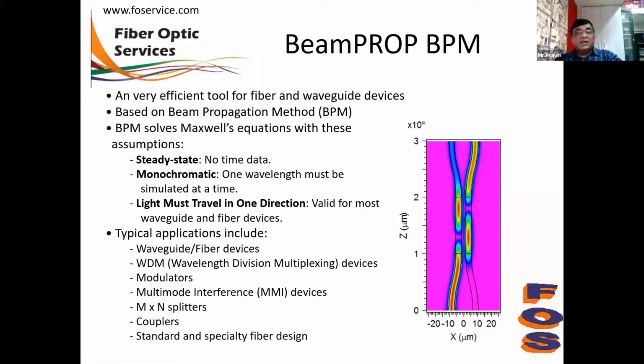In BeamPROP, only one wavelength travels at a time, and light must travel in one direction. So this is the BPM based technique, and it is suitable for waveguides, WDM multiplexing devices, modulators, multi-mode interface devices, splitters, couplers, and standard and specialty fiber design.